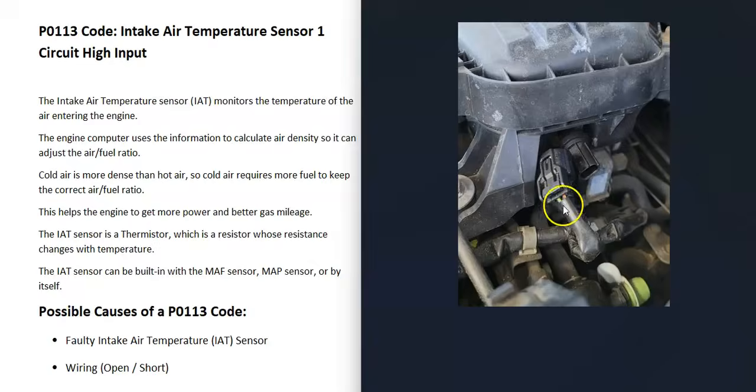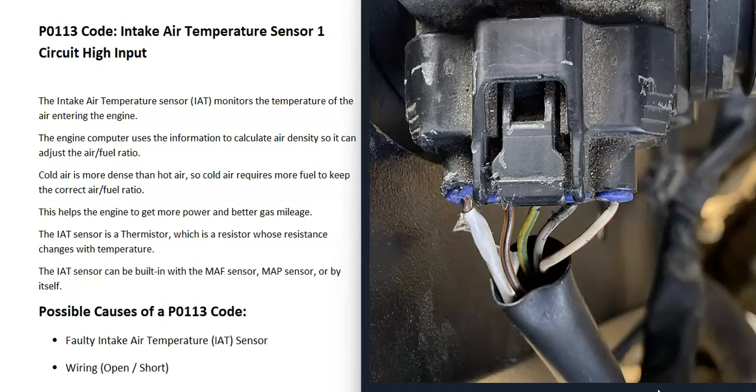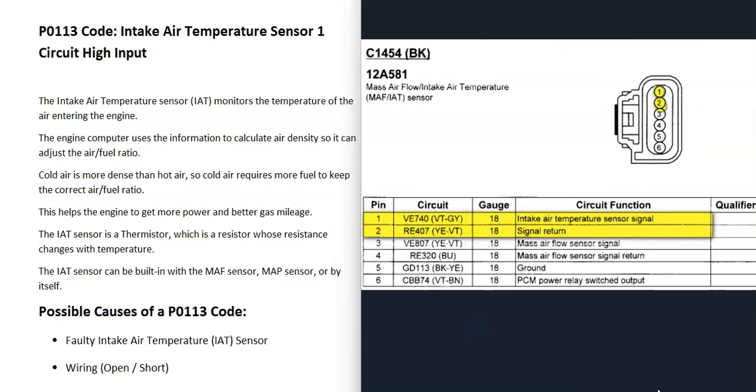The next thing that could cause this is the wiring going to the sensor. If there's anything wrong inside the wiring, like an open, short, or bad connection, then this is going to cause the same symptoms as a bad sensor. So be sure to check out the wiring and see if you see any physical damage to it or anything like that. And make sure the connector is on there good and making good contact. You can also test those wires to see if there's any open or short or anything like that.